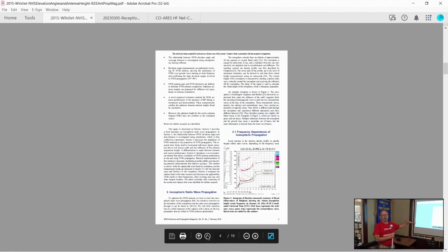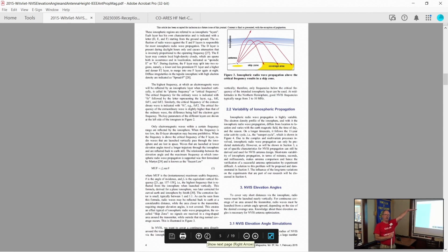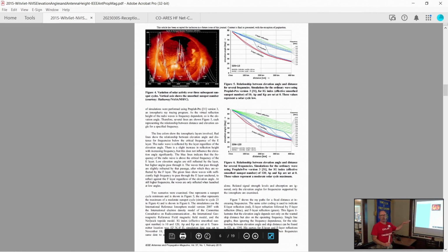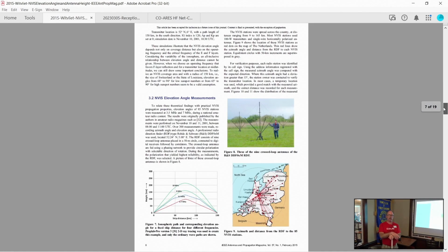And they did a bunch of stuff to measure the height of the antenna versus its effectiveness, height above ground, below a quarter wavelength. So getting down into more practical heights above the ground. And they made some nice graphs of at what point you really start to hurt yourself on transmit. And they also concluded that the best transmit height is different than the best receive height. If you're only worried about receive, you can go lower for your best performance because it's noise versus signal.